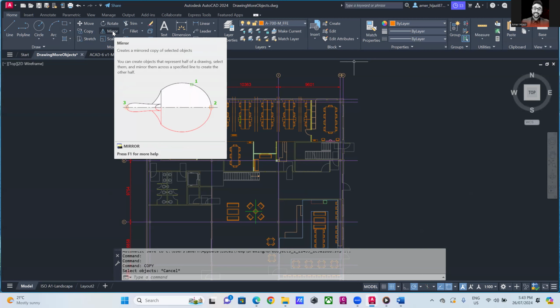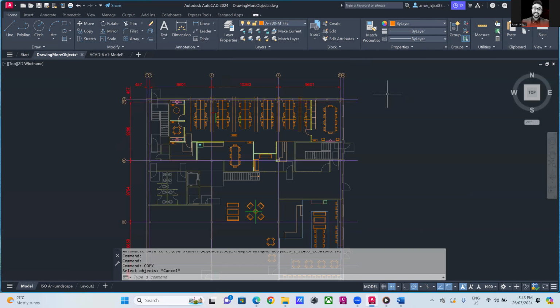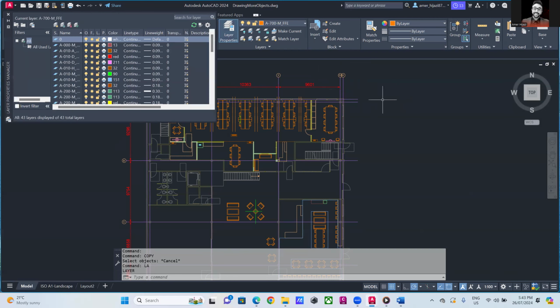But since we're speaking about Autodesk AutoCAD, which is based on lines and layers, something important to figure out is the layer options. Usually if you type LA, for layer, don't worry about all the keys, in time you'll remember them.